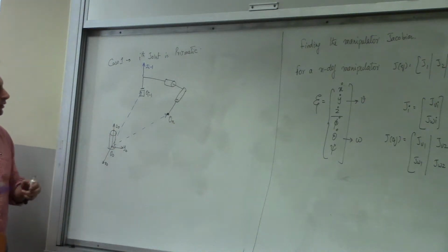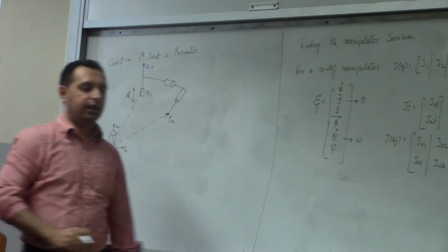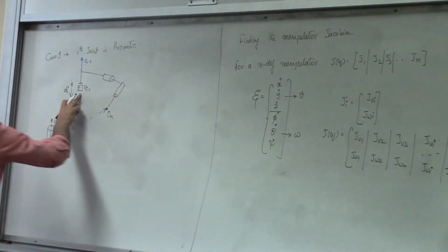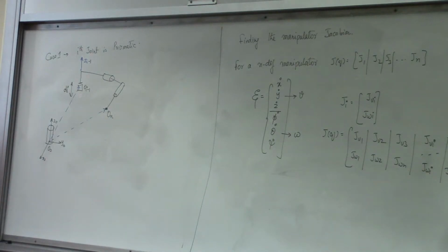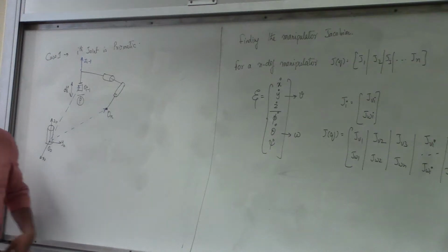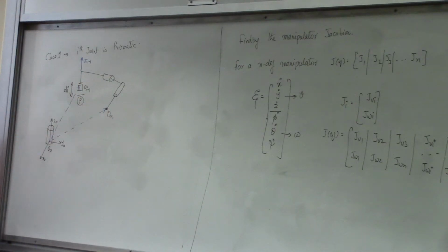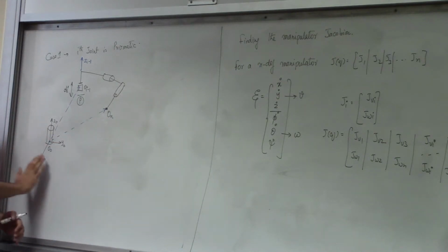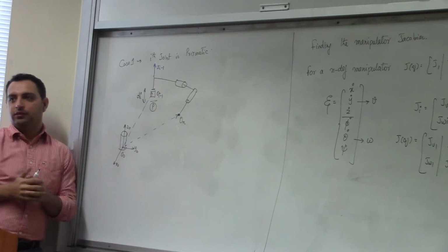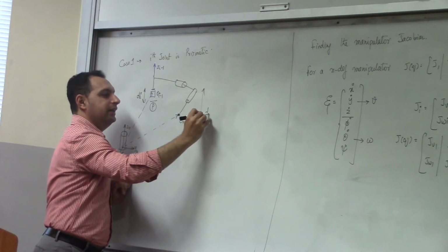Okay. So when this moves, this is a prismatic joint. The ith joint is a prismatic joint. This will be Di. It moves up and down. Di is along Zi minus 1. We are picking one joint within the n joints that the manipulator has, so that we can find the Jacobian at this joint. This is our prismatic joint. So when the joint moves, what is going to happen to On? On is the final wrist coordinates, right? There are always n plus 1 frames. We start from O0 and go up till On. So when there is a displacement along Zi, what will happen to On? Absolutely, it's going to move along Zi, either up or down by Di, whatever it is.